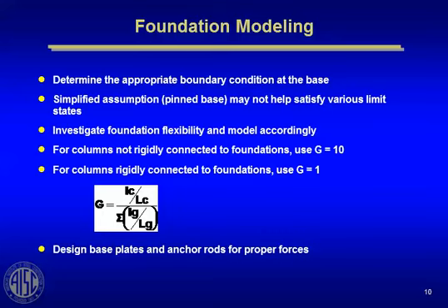I think this is based on a paper by Ted Galambos many years ago that derived this, and it's been part of the nomograph discussion in the AISC specification now for many years. So what we do when we're designing moment frames for foundations is frequently take G equal to 10 and assume a rotational spring at the base that provides that level of rigidity, and then take advantage of that in reducing the drift under a serviceability limit state, which I think is pretty reasonable to do.